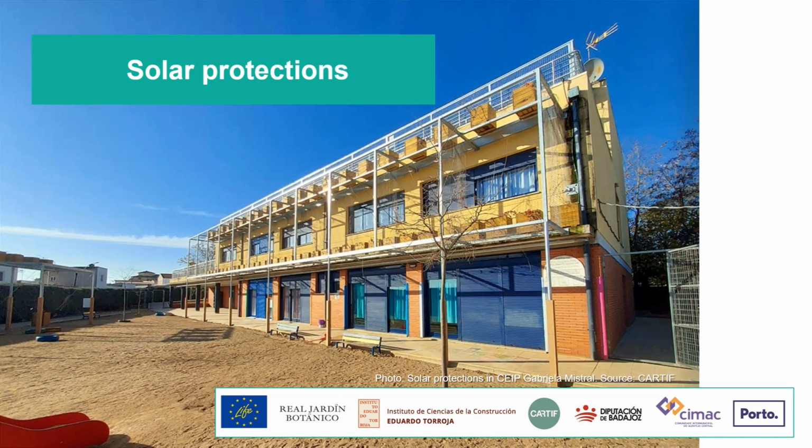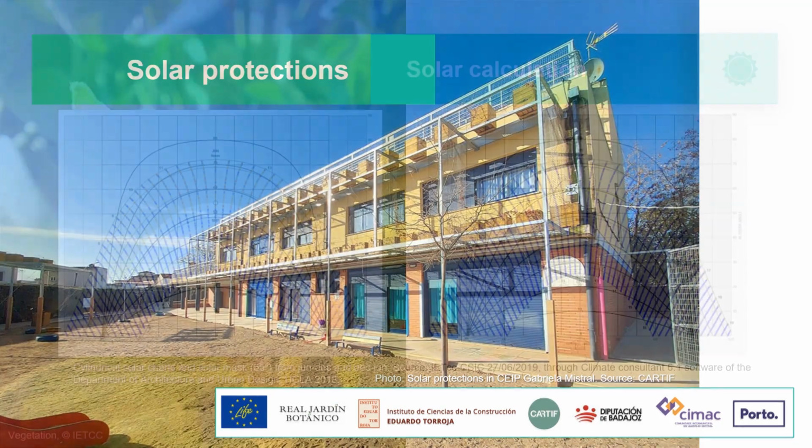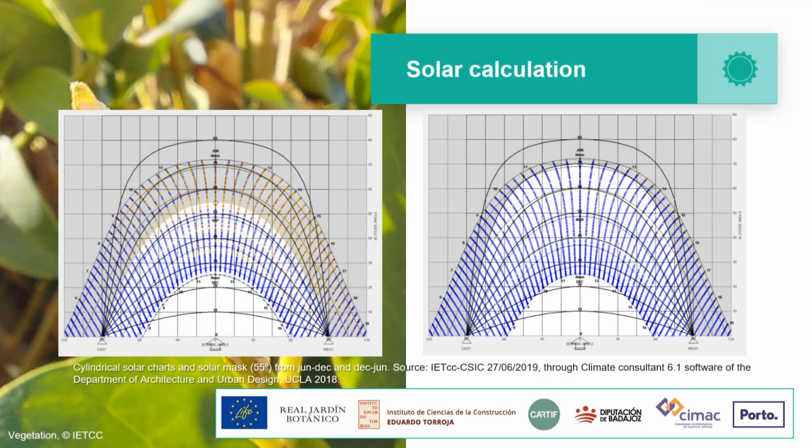For the correct adaptation of these elements to the buildings, their geometry and positioning have been adapted to each case, considering factors such as the thickness of the wall, the existing protection elements, precise orientations, and other parts related to openings. This study intends to dimension the parasols appropriately so that they reduce the solar incidence in summer, but at the same time allow it in winter.